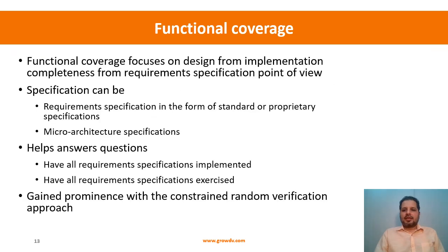Okay, so we have looked at the code coverage. Now let's look at the functional coverage. Functional coverage focuses on design implementation completeness from the requirement specification point of view, right? Whether all the requirements that have been defined are implemented in the design or not is the focus of the functional coverage.